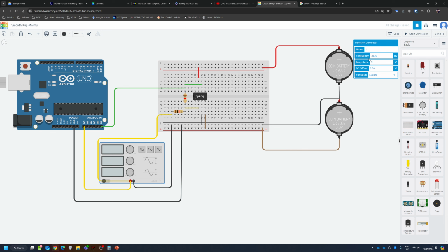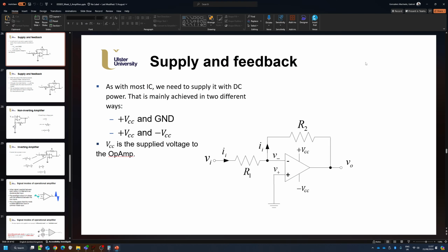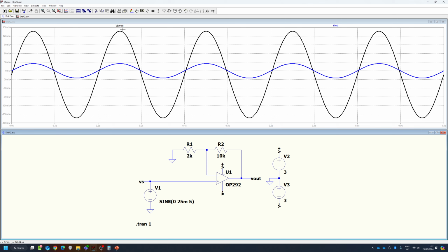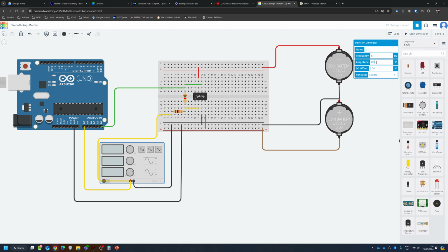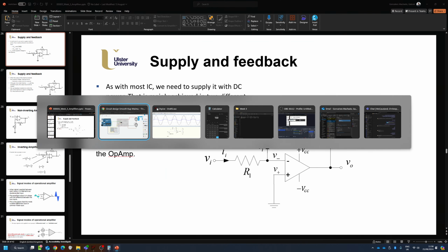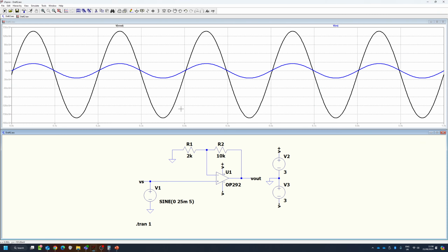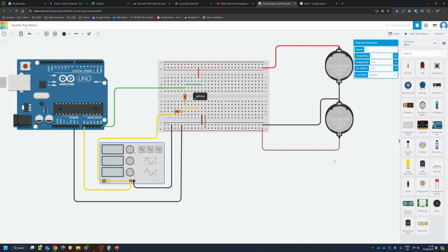Let's now configure our signal generator. Let's put 5 Hz here as well. The amplitude, let's make it 0.5. And in here, amplitude is not the amplitude of the wave, it's the peak to peak. So from here to here, it has 0.5 volts, meaning that from 0 to here, this has 0.25 volts, as we had here, but instead of 25 millivolts, I'm putting 250 millivolts. So the analog to digital converter can work well.